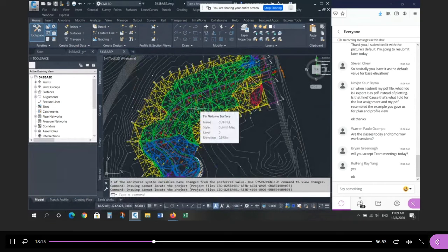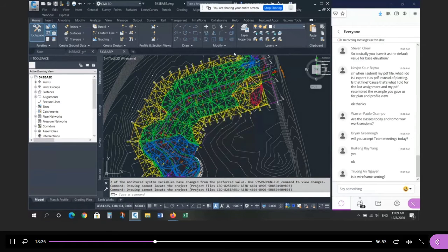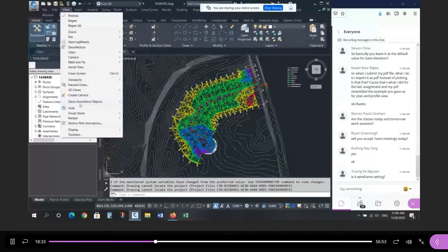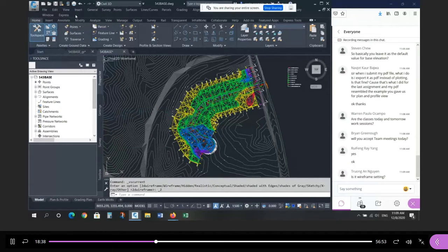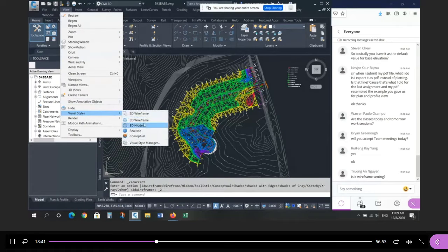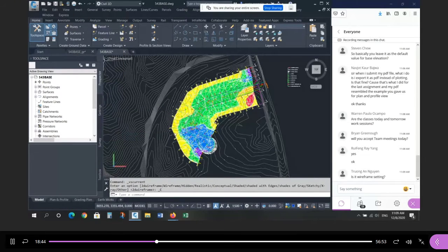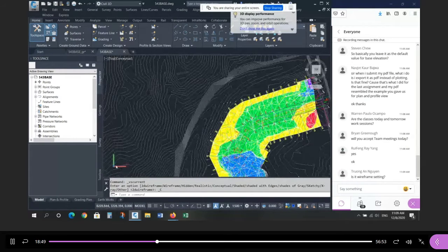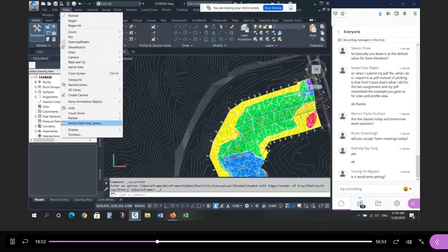There's a few settings in AutoCAD I've already explored. I don't know if any of you have seen this before or have experienced this or are smarter than I am, because I haven't been able to figure it out. Ray, I looked at it just before class again. I went to View, Visual Styles, and it is 2D wireframe. If I change it to conceptual or realistic, the color comes in, but you can still see all the lines, the edges, and that's not the effect we're looking for. See the icon changed? That's kinda how to show it, but not really.